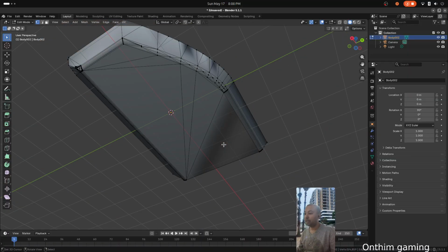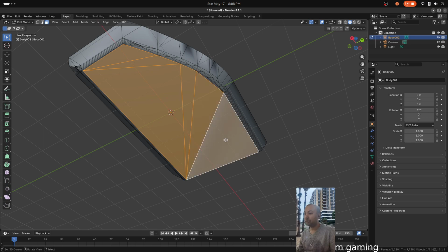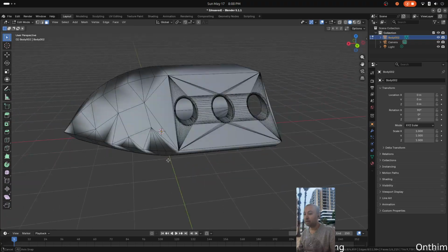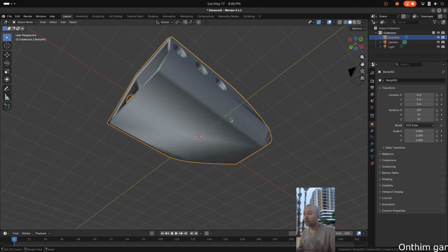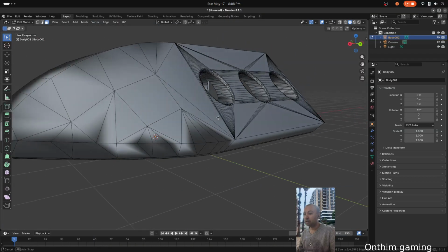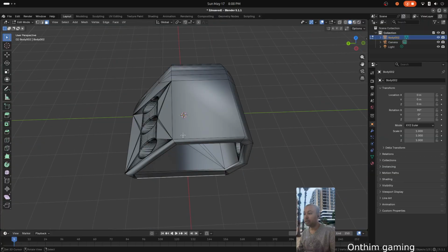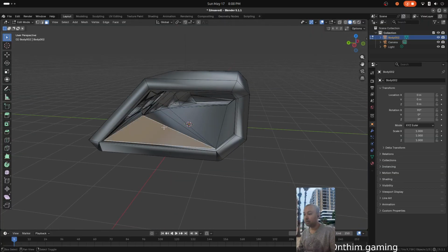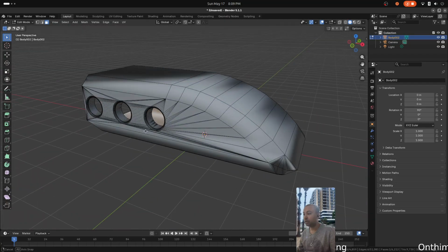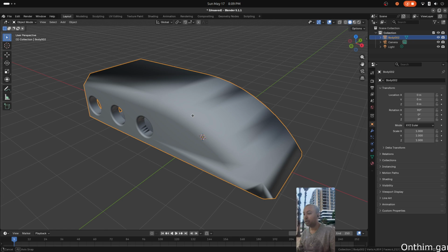So this is a flat face. I'm gonna select all these flat faces and then just create an n-gon, right? Because this is just one big piece of flat, and then you can start doing little modifications like that. The main idea is that regardless of how the mesh is arranged in terms of triangles, quads, or n-gons, the shading should be great.